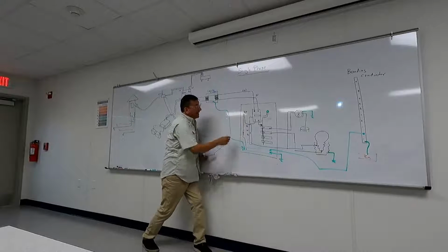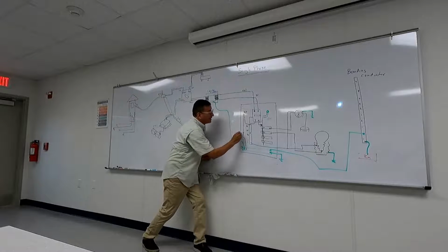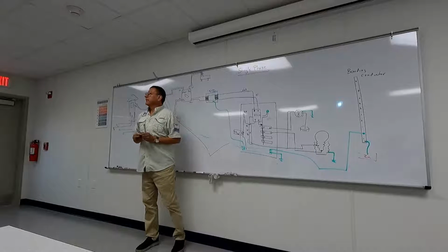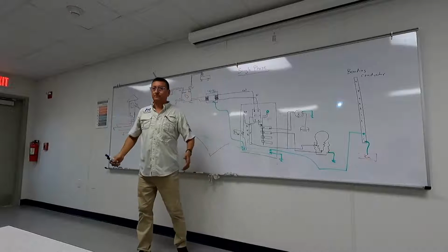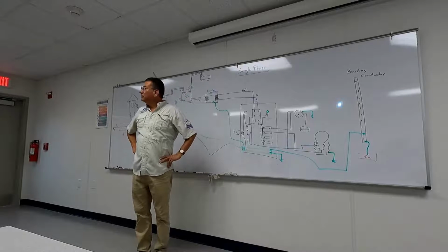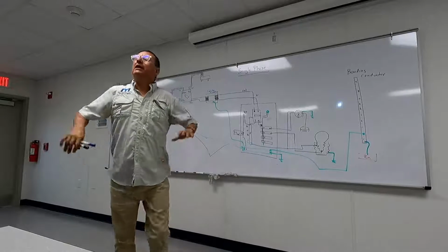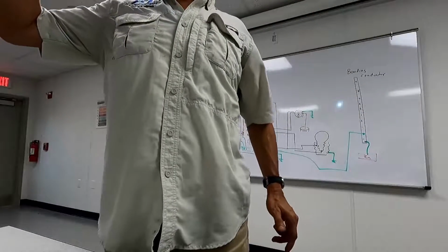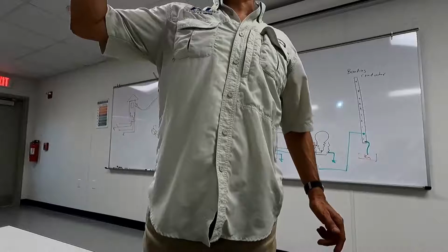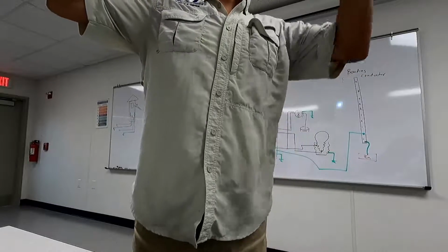That LED has a resistor; the value of the resistor is 2.5 kilo ohms. ABYC question. It's an LED, a diode. All the AC panels, single phase, have the LED light for reverse polarity and the other LED for power.